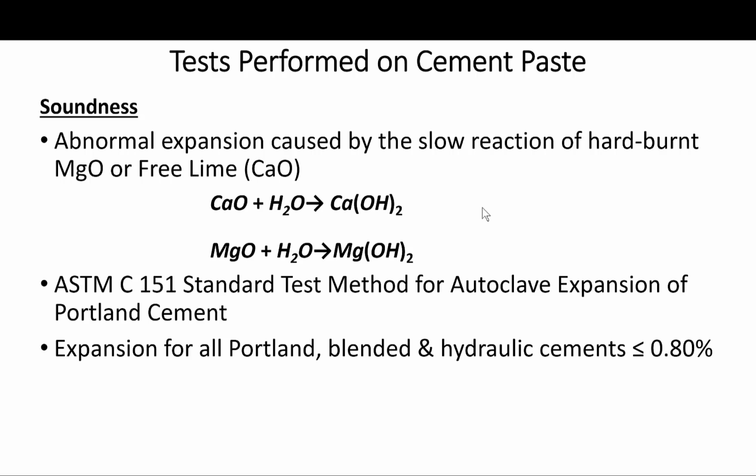Although a number of soundness tests have been developed over the years, only one is in common use. This is the autoclave expansion test according to ASTM C151. This will detect unsoundness due to both excess calcium oxide, free lime, and excess magnesium oxide. And this is the test designated by ASTM C150. Okay.